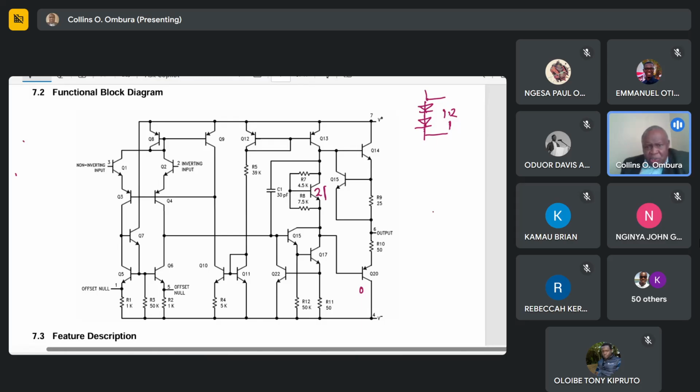So the function of Q21 over there is to put a voltage approximately ranging between 1 and 1.2 volts across the base of Q14 and Q20. For example, let's start with the top transistor, which is Q14. For this transistor, just to conduct, the voltage between here and here, because this is a low resistance, should be approximately the cut-in voltage when you're just starting to have crossover distortion. Should be 0.5 volts with this side positive, this side negative.